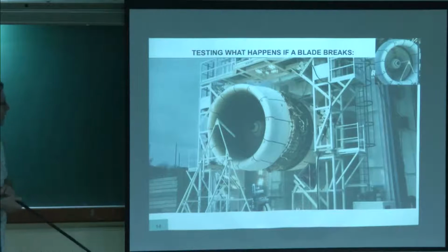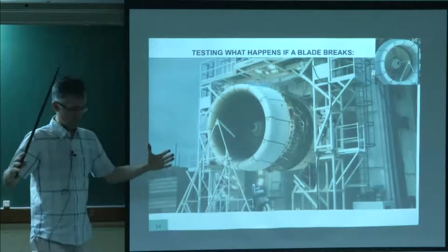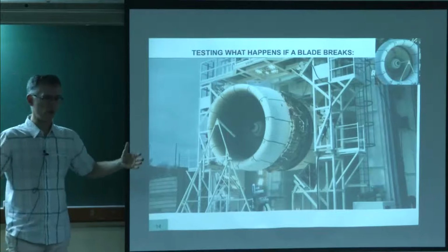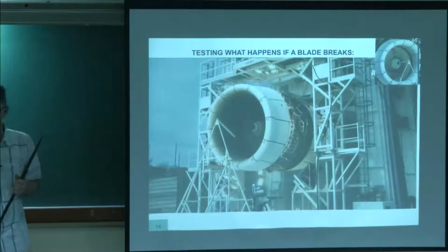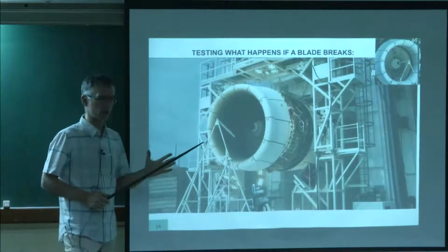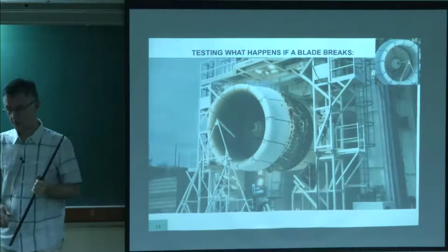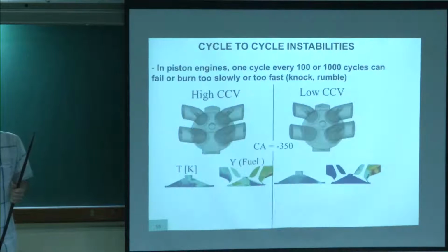Siemens, for example, they know this problem. If you have something breaking, it's a piece of metal which can be big like this, flying at a speed of Mach 0.7 or 0.8. So it can travel for kilometers. So it's extremely dangerous. So anytime you start having vibrations, for example, due to combustion instabilities, then you basically have to stop the engine, and then it's going to cost you.